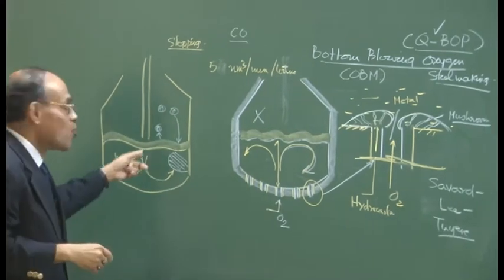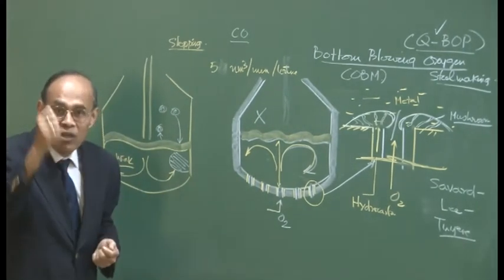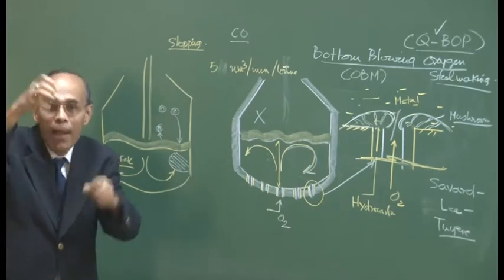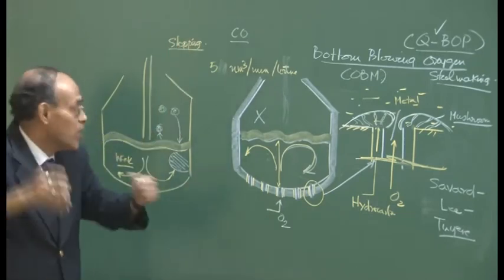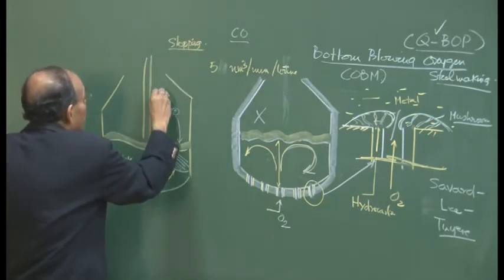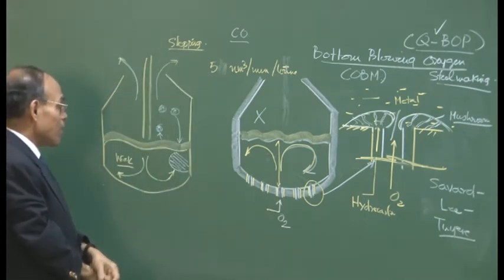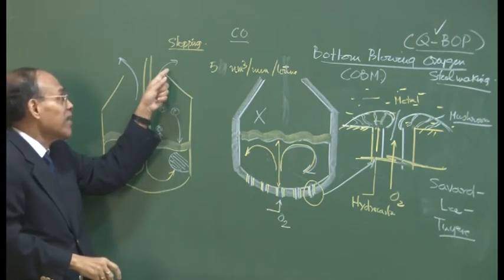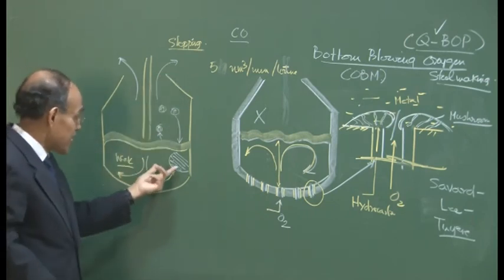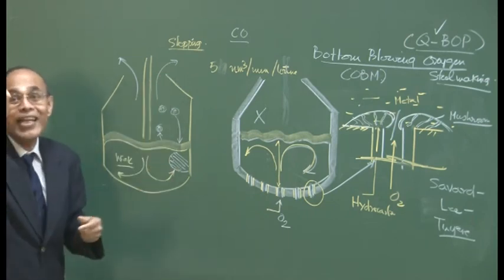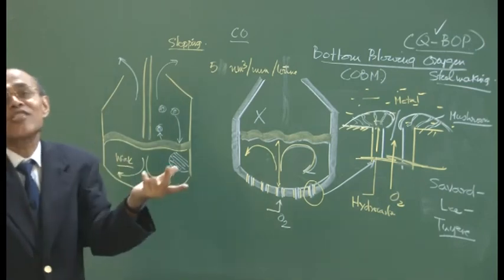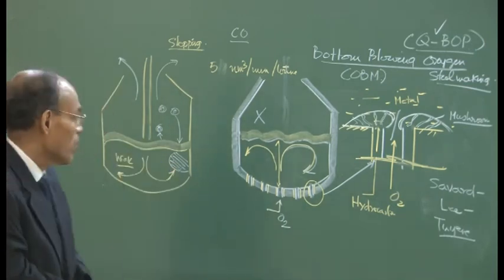Okay? The scenario is equivalent to taking a Coke bottle, shaking it, and then opening the cap. What happens? The cola comes out, and it is exactly the same way that the material comes out. There is gas, metal, slag, everything comes out. As a result, your yield decreases. You have lost some amount of hot metal, iron, from the system.